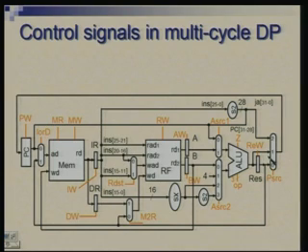One more thing which you should see here is the way Z is going to be used. In the single cycle design, we used Z directly to control a multiplexer through AND gate. So, there was a signal coming from controller that was ANDed with Z, and then we controlled the multiplexer. Basically we were making a choice between PC plus 4 and PC plus 4 plus offset, one of the two going to the PC.